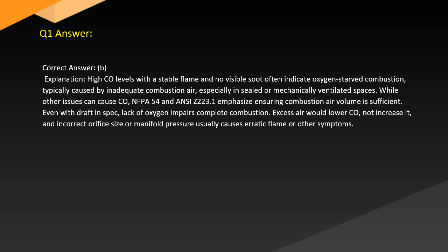Excess air would lower CO, not increase it. An incorrect orifice size or manifold pressure usually causes erratic flame or other symptoms.